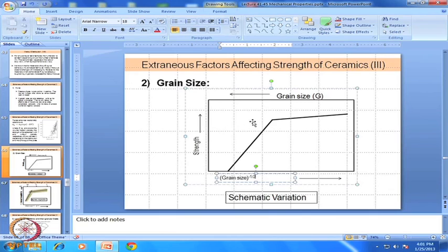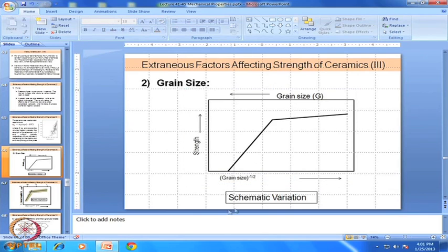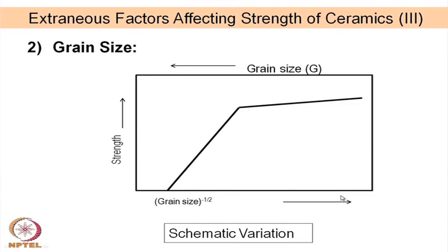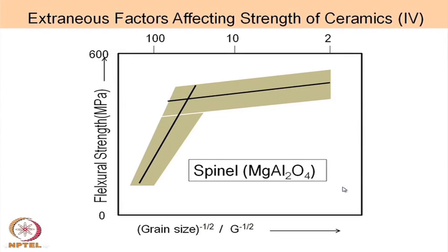It is the intergranular fracture which controls the strength of the material, and therefore, finer is the grain, the crack size is finer, and therefore the strength is also higher. So, that is once again a kind of empirical situation so far as the effect of grain size is concerned. That was a kind of theoretical curve, but in actual practice you get more or less the same behavior.